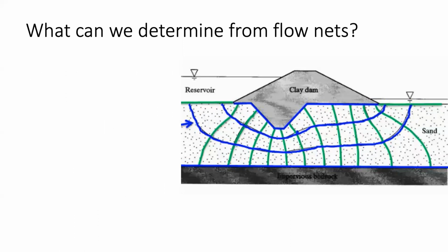So what we're going to do is first draw in our equipotential lines, right? Let's say we start at 10 over here and we drop to, let's say, 1 over here, and we may be putting in equipotential lines along these flow paths, each of these representing the same head drop. So if this is a half a meter head drop, each one of these lines would then represent that contour.